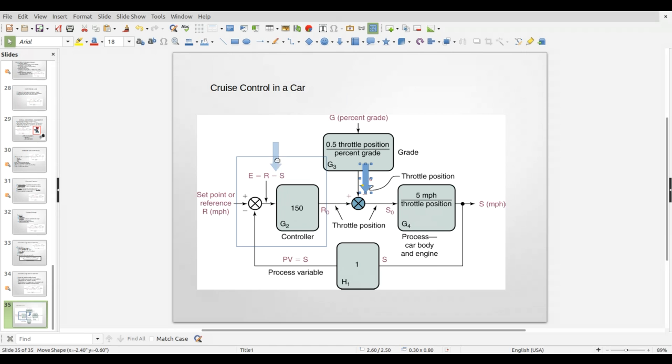And so therefore we need to increase our throttle so we can go faster to maintain our desired speed, right? Because we've already slowed down because of the disturbance. And that's the idea of any sort of closed loop system, is we want to be able to react to any disturbance in the system.